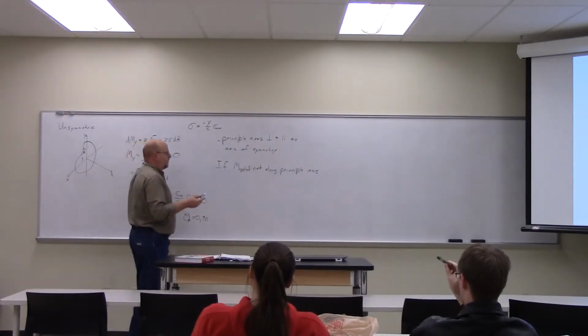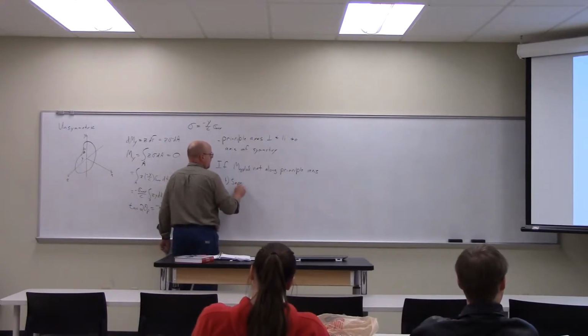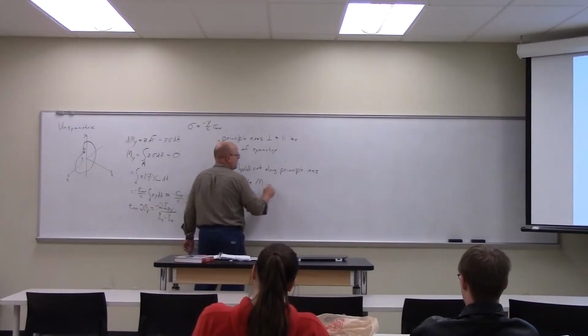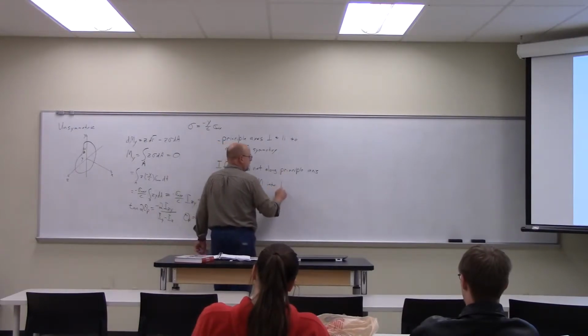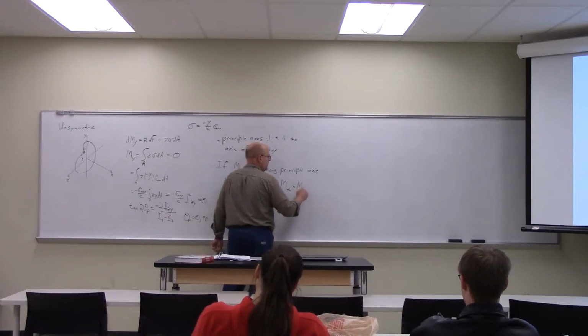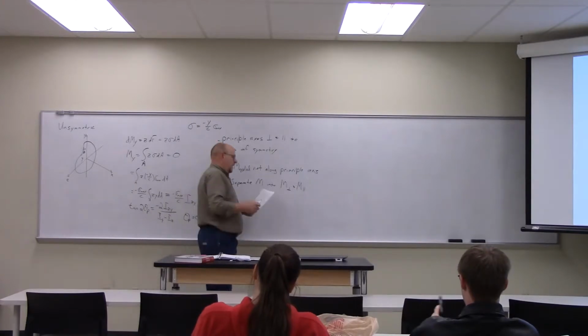Fine. Okay, so if it's not, what do we do? First step. Separate the applied moment into a piece perpendicular to and a piece parallel to the principal axes.